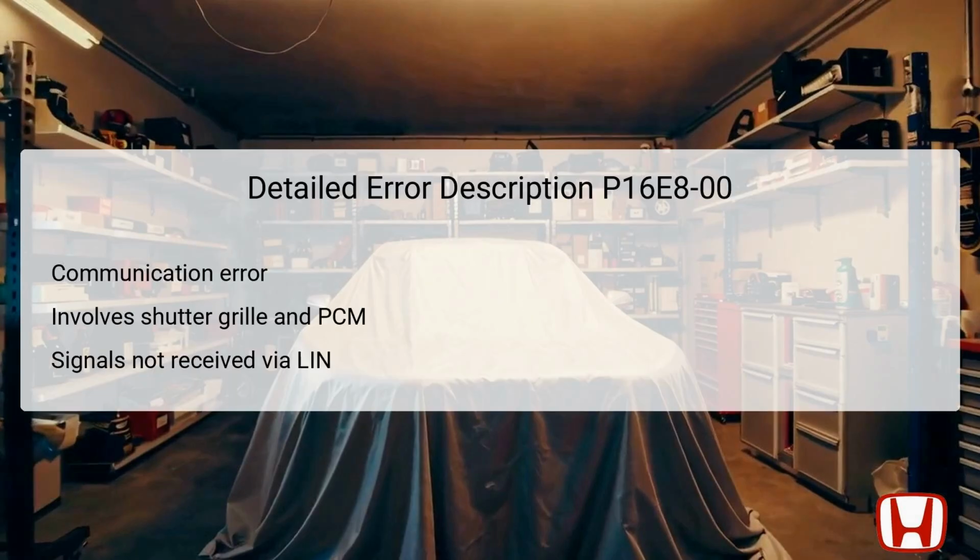The P16E8-00 code signifies a communication error between the shutter grille and the PCM via the LIN system. The LIN, or Local Interconnect Network, is essential for low-speed communication between various electronic components in the vehicle, including the shutter grille and the PCM.